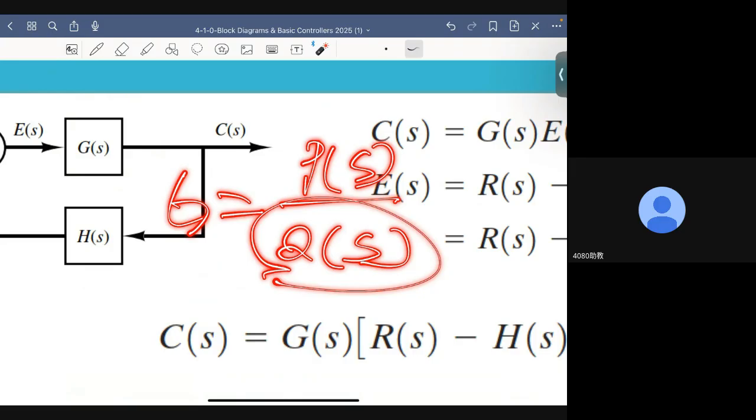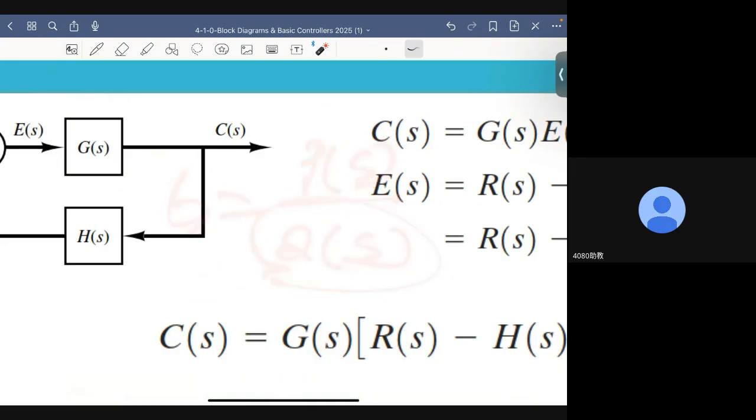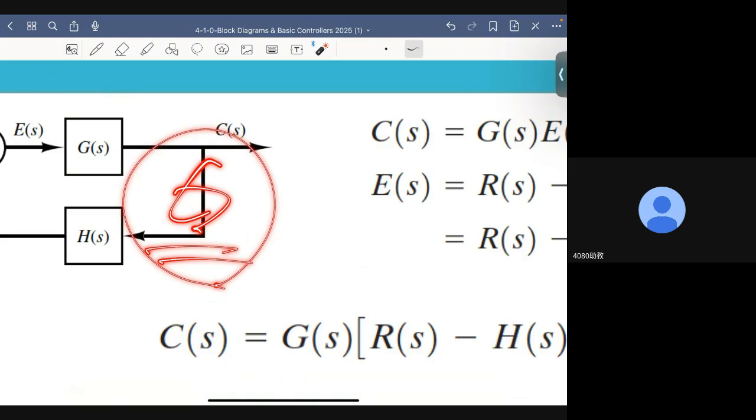And you know, when poles are located in some regions, it may not provide satisfactory or fast enough transient response. Its stability can be questionable. In any event, in the open loop configuration, the poles may be located in some undesirable region.